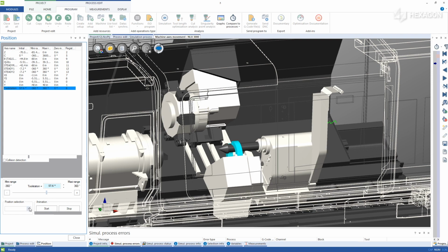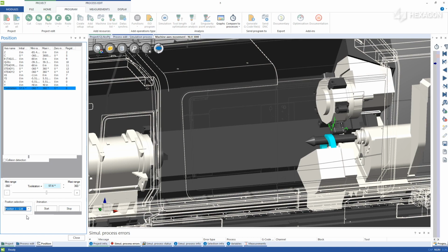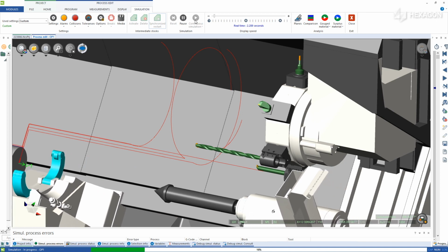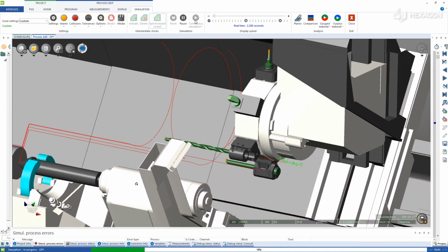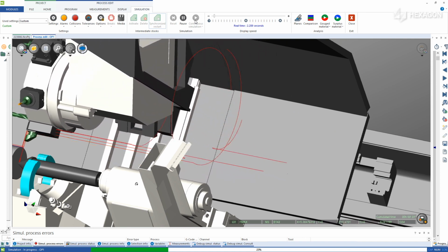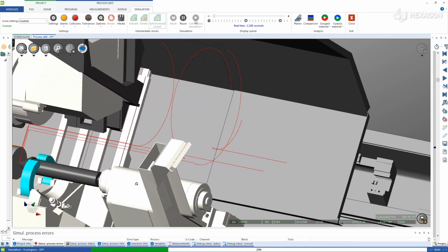Additionally, you can call a specific G-code that the shop is using, such as the G28 here, and jump all axes to this alignment. Stepping through the axis motion can allow for easier visualization of the machine movements, especially on machines that are tough to see inside, speeding up the time to produce a final part.